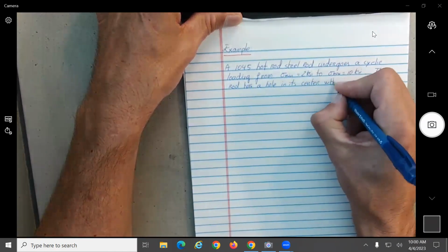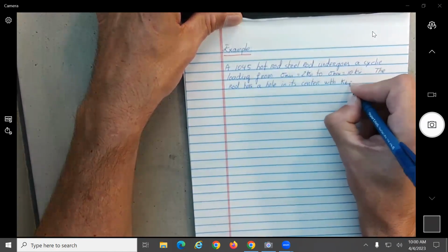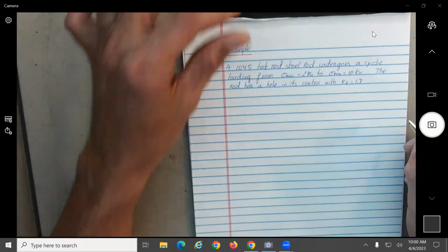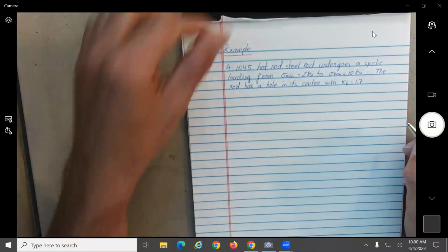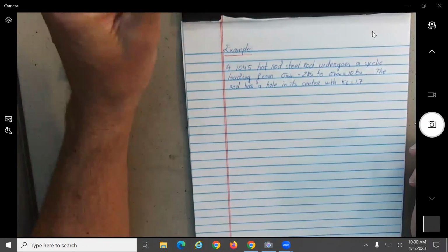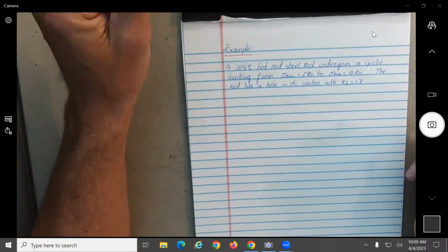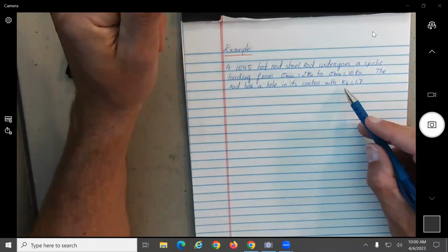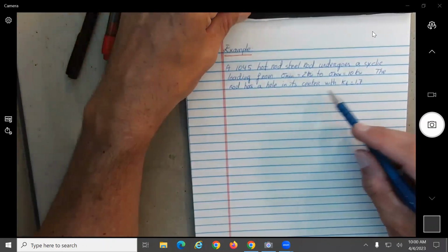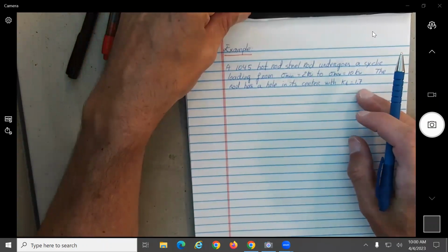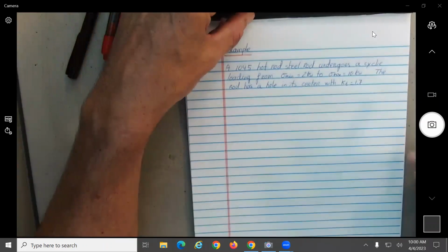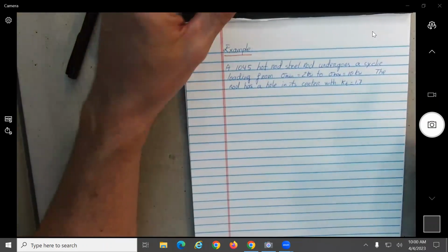with what is KT? Look at it last time. What is it? 3. What is it? Oh, the value? No, what is the meaning of KT? It is a stress concentration factor, no? Okay, so in this case, the hole is said to augment the stresses by what? By 70%, basically, no? 1.7. I think it's supposed to be 3, no? For a hole on the other ones, but in this case, they say to use 1.7.